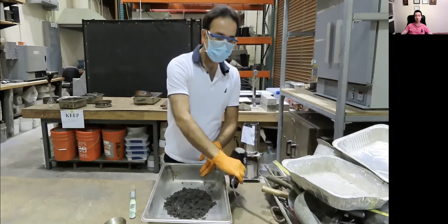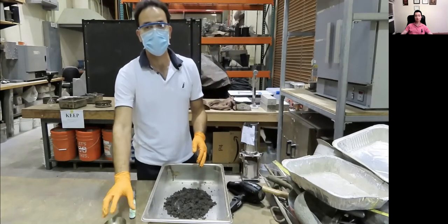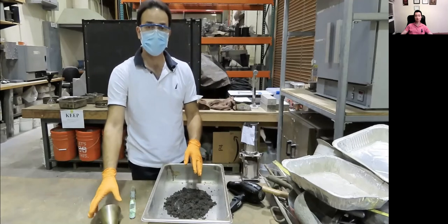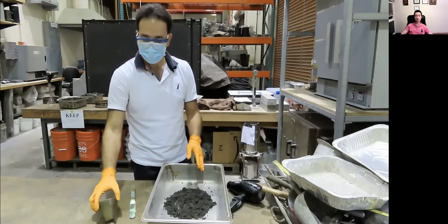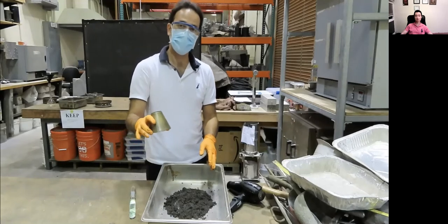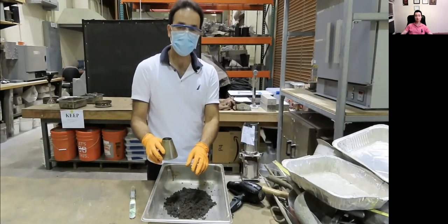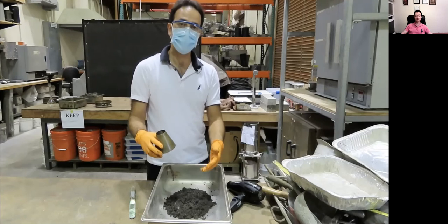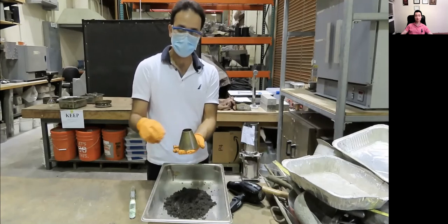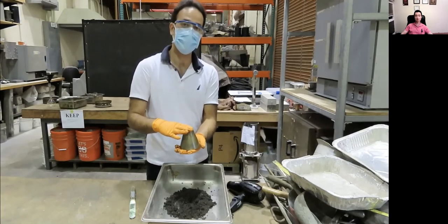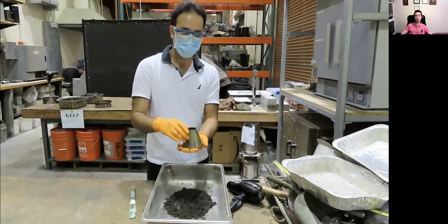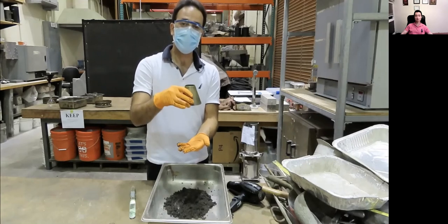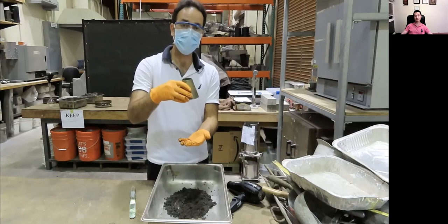The only way that I can make sure that my fine aggregate is in SSD condition is using this small cone. I need to pour all the fine aggregate that I think is in SSD condition in the cone and then tamp it 25 times gently, I'm going to show you, and then pull out the cone gently and vertically.